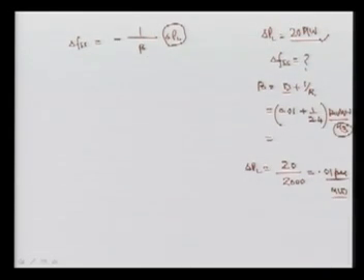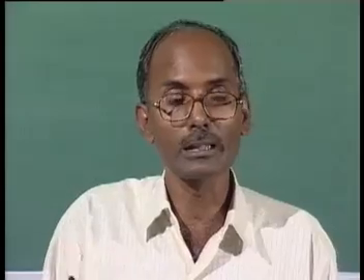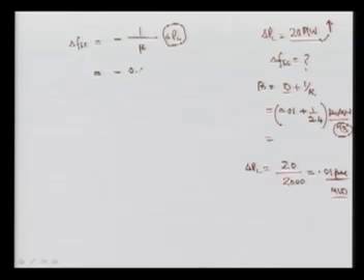Now, if this value is increased, let's suppose that the 20 megawatt is increased, I can say this is a positive value. If it is decreased, then it will be a negative value. So this is positive, so I can say minus 0.01 divided by this value, and that value is 0.01 plus 1 over 2.4, and we are going to get this value in hertz. This quantity is negative, which means there is a fall from the 50 hertz.